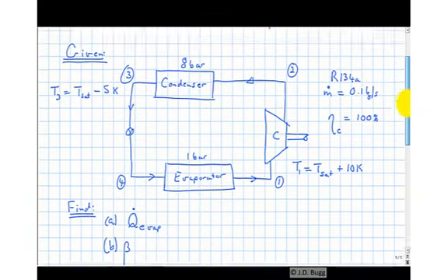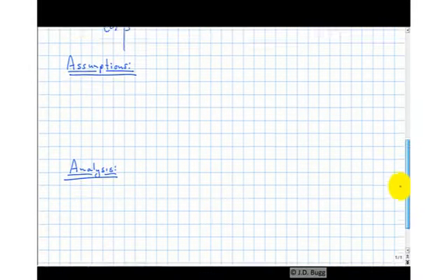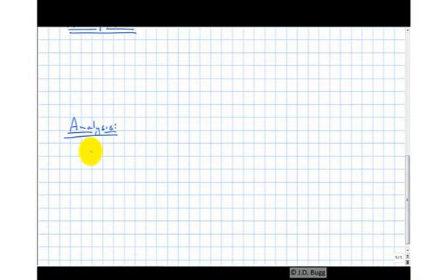after. Now, in any of these problems where we have multiple components like this, we're always going to end up applying the energy equation multiple times. So what I suggest we do here is right off the bat start with our most general energy equation and make all of the assumptions that we can make for every component and simplify it down to one that we can then apply to each component. So starting with our general energy equation.